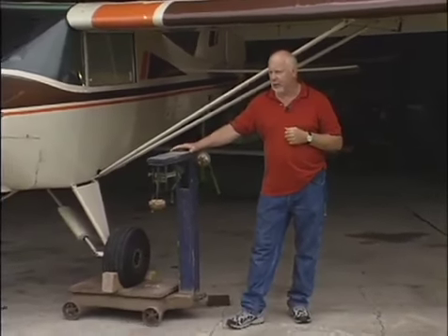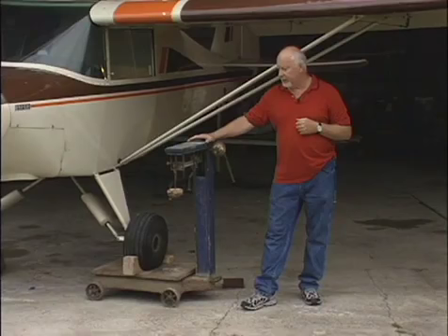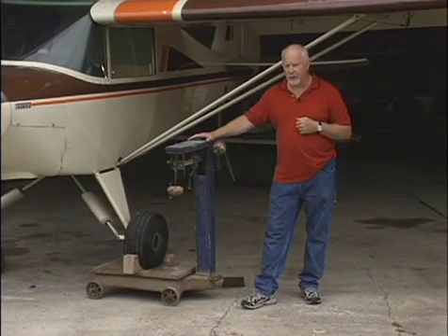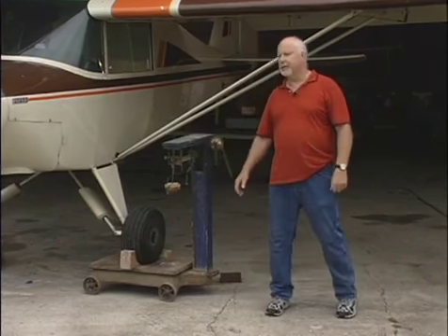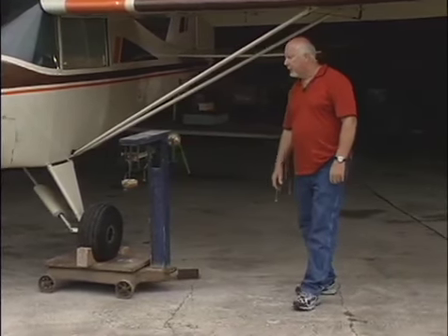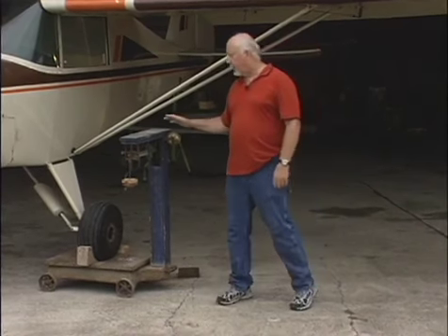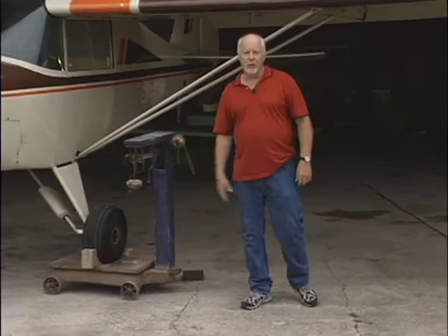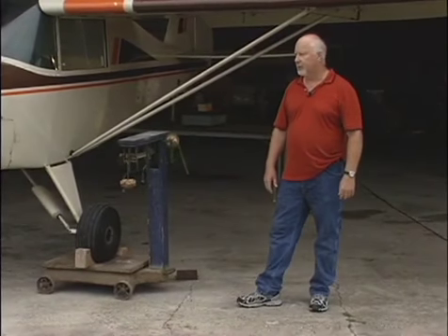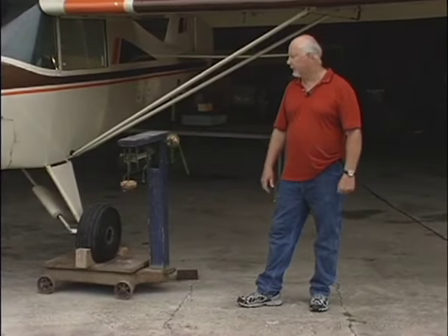We started out with the scales. It's ideal if you can get scales that have been calibrated. If they haven't been calibrated, try and calibrate them yourself. Get some weight that you know of, try it on the scale, and make sure it's accurate. We did that with all 3 scales, and then the next thing we did was zero them to make sure that we're starting off at 0 when we weigh the aircraft.